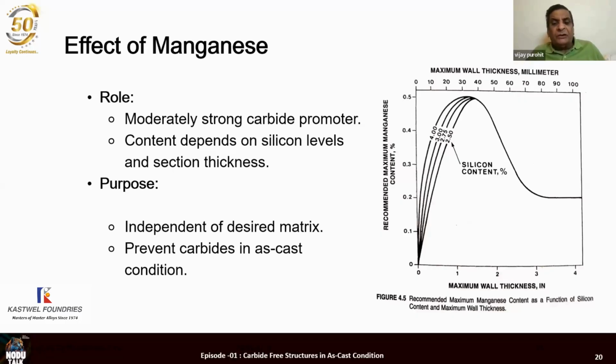And this manganese in the heavy section creates such a stubborn carbide that if you are doing any drilling operation, first it will wear out the drill. The drill will not move any further. In the worst case, it will break the drill. People don't realize that. Your machine shop will come howling at you. So please don't use manganese as an alloying element.